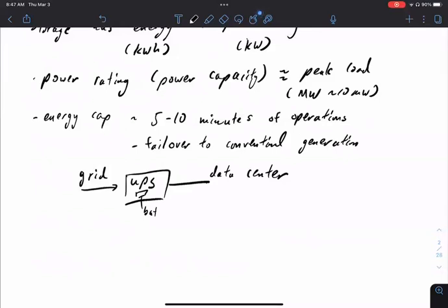This kind of data center building has an issue. Right. So this has a single point of failure. Essentially, the single point of failure is this UPS, because it's a big battery. This is a complicated UPS. There's a lot of high power switching going on here. That tends to burn out your UPS. If this goes, the entire system goes.